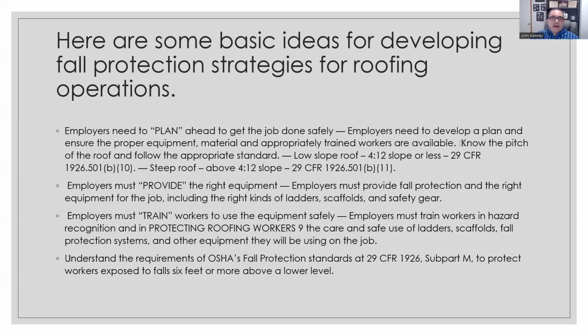Employers need to plan ahead to get the job done safely. Employers need to develop a plan and ensure proper equipment, materials, and appropriately trained workers are available. You need to know the pitch of the roof and follow the appropriate standard. Low slope is 4 on 12 or less. That goes to 29 CFR 1926.501(b)(10), right? Go to OSHA, look that up. Steep slope is above 4 on 12. And again, same area, except the last part is subpart (b)(11).